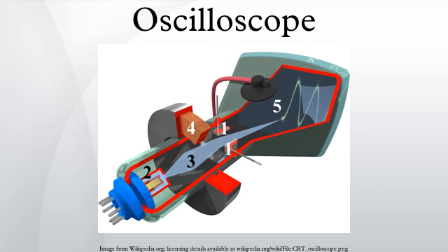Delayed sweep controls. These include controls for the delayed sweep time-base, which is calibrated, and often also variable. The slowest speed is several steps faster than the slowest main sweep speed, although the fastest is generally the same. A calibrated multiturn delay time control offers wide-range, high-resolution delay settings. It spans the full duration of the main sweep, and its reading corresponds to graticule divisions. Its accuracy is also superior to that of the display.